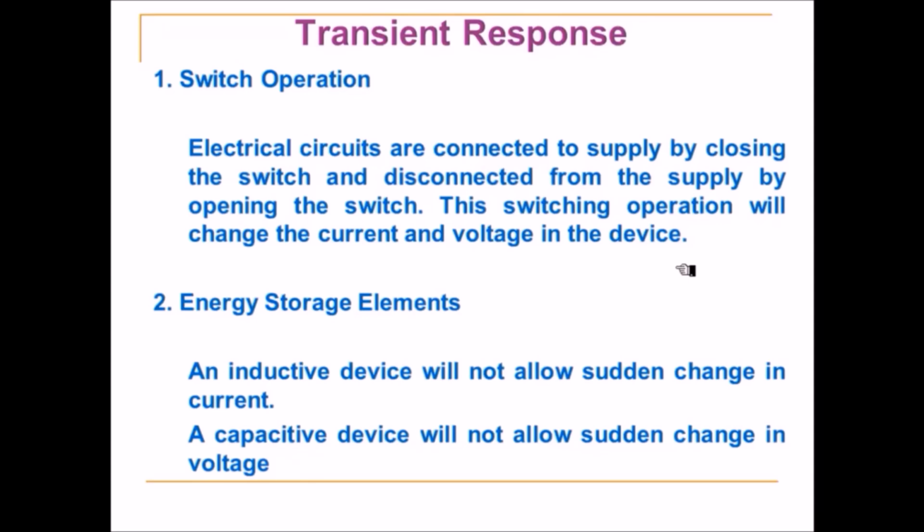The second reason is the presence of energy storage elements. If you have energy storage elements in the circuits, such as inductors or capacitors, and you apply input to the circuit, the energy storage elements will not accept the inputs immediately. It may take a small amount of time to accept the inputs and store the energy. Similarly, if you disconnect the supply from the circuit, it will not release the energy immediately. Again, it will take a small amount of time to release the energy.